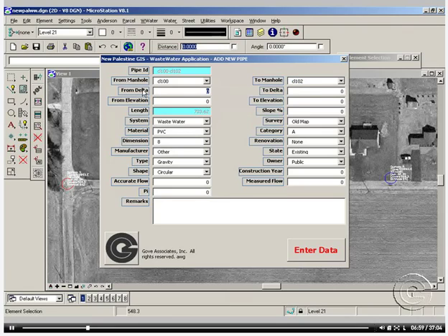As we can see here, you see the deltas. The deltas are the differences between the cover or rim elevation of the manhole and where the pipe is either leaving the manhole or landing onto the manhole. So the delta allows you to calculate the invert elevation. Let's say here the delta from one is 2, and then the delta from the other one, let's say, is 3.5. And again, as we enter those deltas, the program calculates the invert elevation for that pipe.